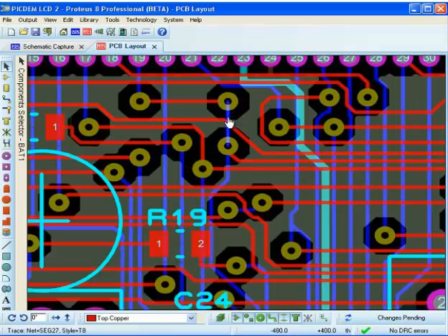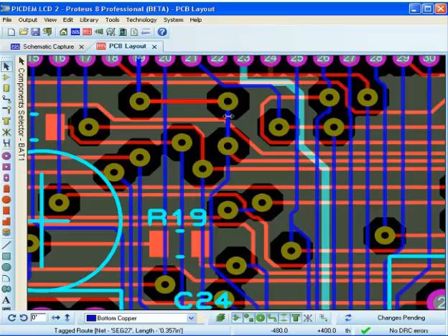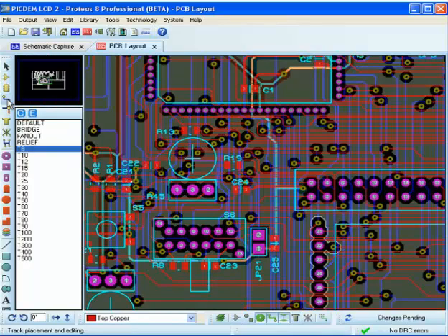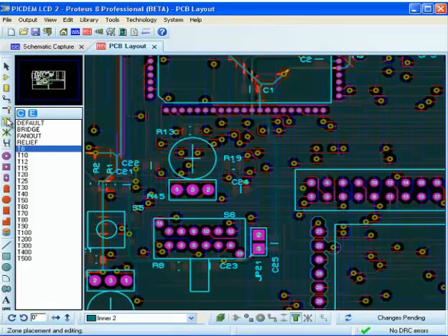Essentially, as you select items on a particular layer, that layer then becomes the current layer. This is very intuitive because the current layer is displayed most prominently. The Through View technology is still active and allows us to see the other layers. It should also be noted that when you select between the trace function and the zone function, the zone then becomes most prominent on your display when you're working with your power planes.